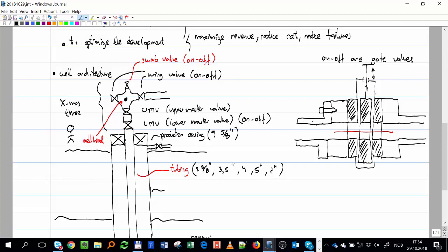That's something very important for production engineers and something that we can get a lot of value out of. If we manage to measure wellhead pressure, that has a lot of value. But to measure that, I'm not allowed, because of integrity reasons, because of safety reasons, to put just a pressure transducer here, just below the master valve, because that opens a potential leak path. If I make a hole, then I might have a leakage there. So I created a leak path.